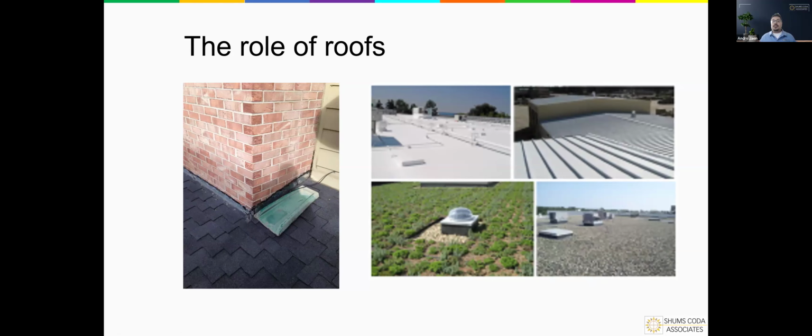In some jurisdictions, they will allow continuous flashing as well, and more recent generations of the code have gone back and forth on that issue a couple of times. You'd see head wall flashing, which is basically an L-shaped metal flashing that runs under the shingles here that are running basically perpendicular, or parallel, excuse me, to the wall. So the leading edge of that shingle.